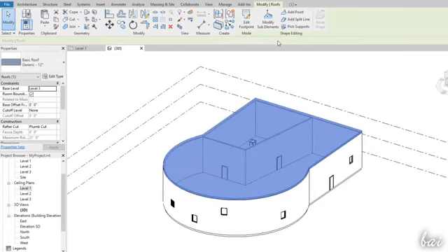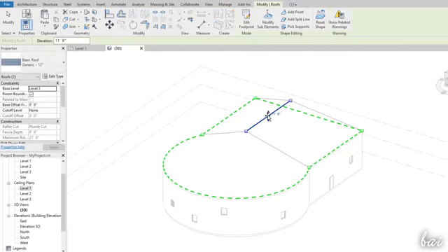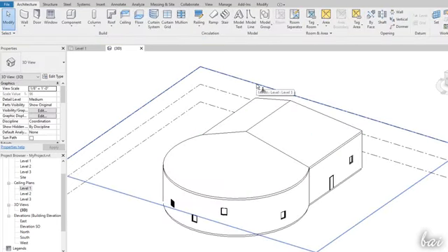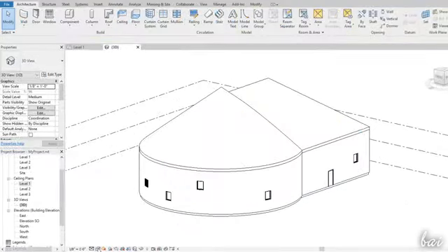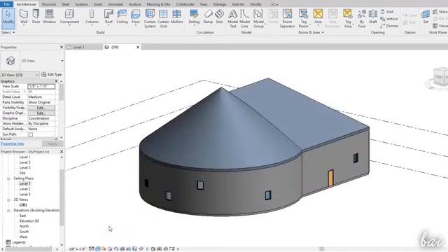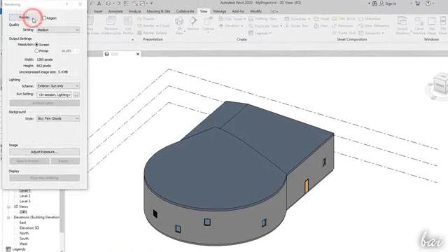and you will be able to fully customize it with the Shape Editing section above. You can use Add Point and Add Split Line to add vertices and lines on the roof, and then use the Escape key and modify sub-elements to move and edit these to define the slopes. Use Reset Shape above to undo all and come back to a flat roof. To adjust the object preview, use the Visual Style buttons at the bottom. Whereas to get a more realistic preview, you can go to the Render button under the View tab.